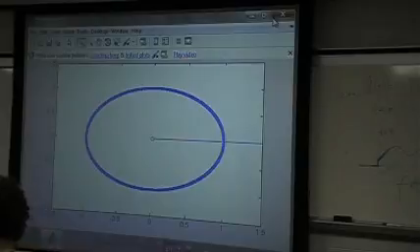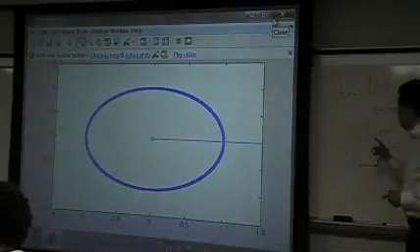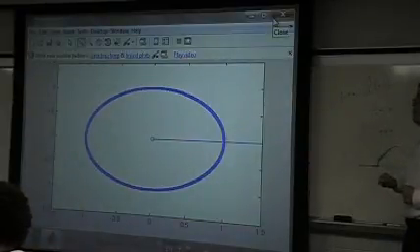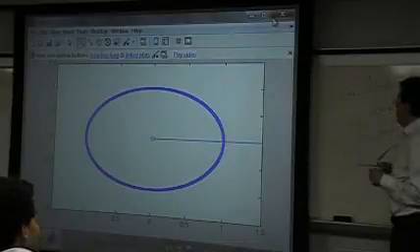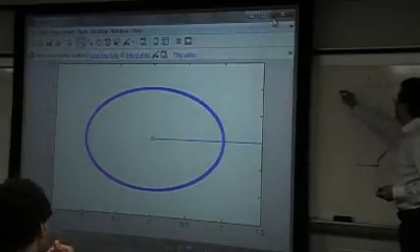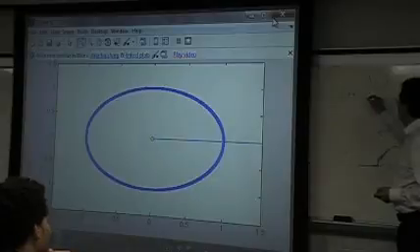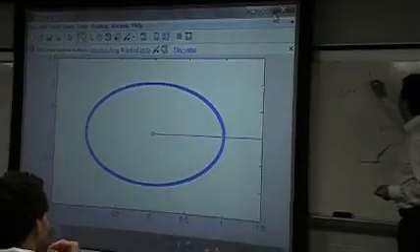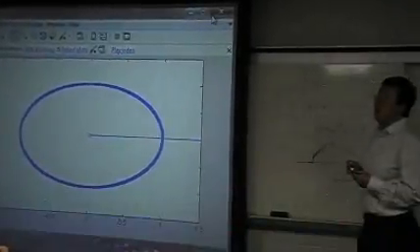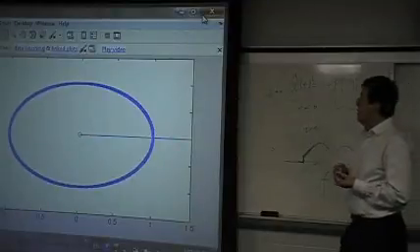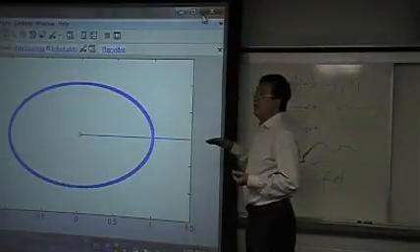So the line is alpha pi by 2, right? Yeah. Alpha is 0.001. This is the value of alpha, and the line has a slope of pi over 2 times alpha. So that means the poles have to lie in a really small region for the system to be unstable. Yes.